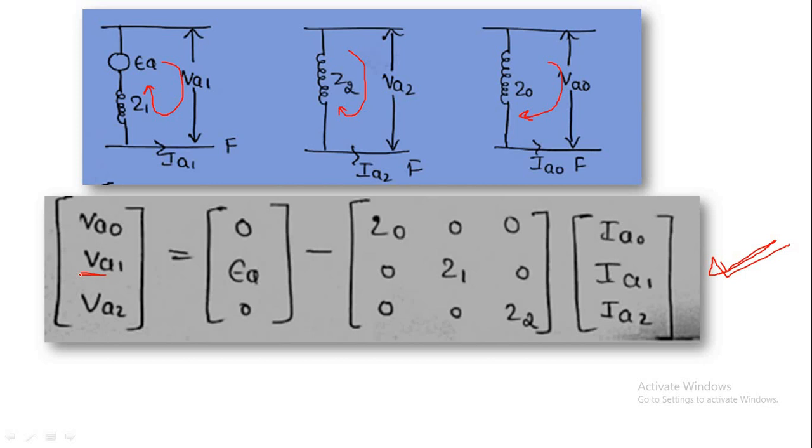We can write this in matrix form. Before that, these equations can be called the system equations. For any fault at the terminals of a synchronous generator, the quantities to be determined are the three sequence currents IA1, IA2, IA0, and the three sequence terminal voltages VA1, VA2, VA0.